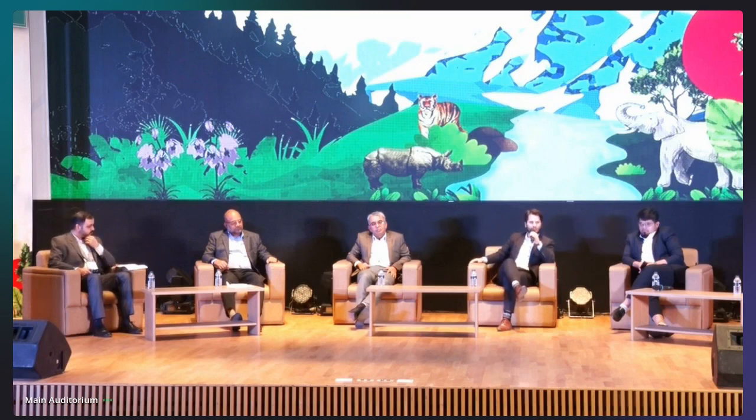Not a good thing. So if we can program those vehicles so that instead of charging at 8 p.m., they start at midnight, we're shifting the demand. And we are shifting demand in a way that is better for our supply situation, because at midnight it's the super off-peak tariff. So it's also cheaper. Economically, it makes sense.